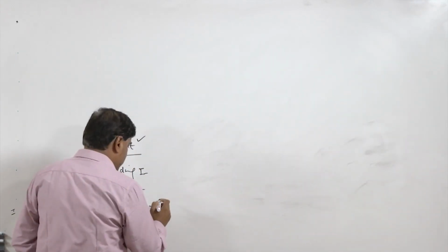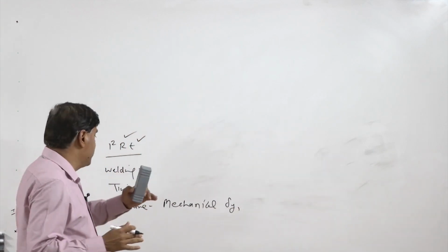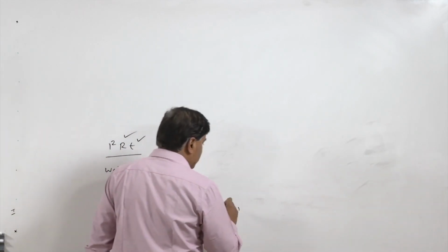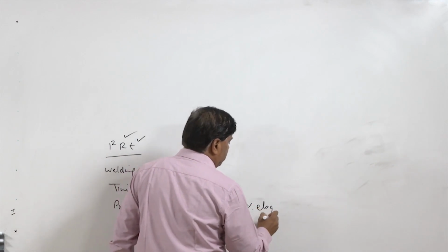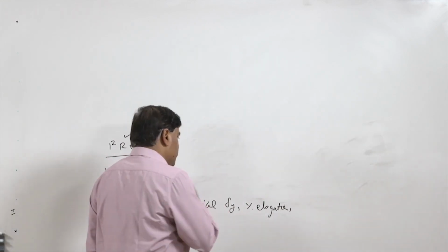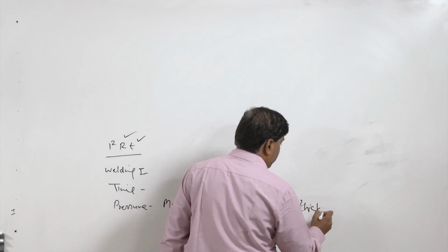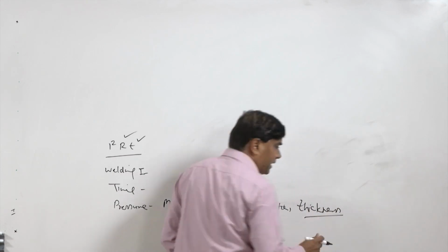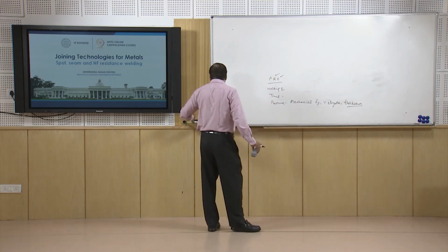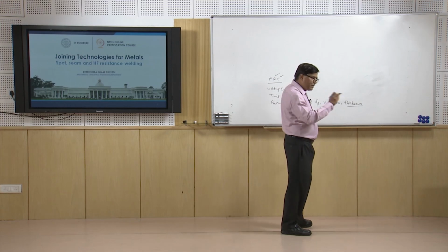material. So these factors are, in mechanical properties, the yield strength of the material. High yield strength materials require greater application of the load in order to achieve the kind of metallic intimacy which is needed, and the percentage elongation. High ductility materials will require lesser load or pressure as compared to low ductility materials, and similarly the thickness of the sheets being welded. So thicker sheets will require more load, heavier pressure as compared to thin sheets, in order to ensure the desired contact between the workpieces at the faying surfaces or at the interface.